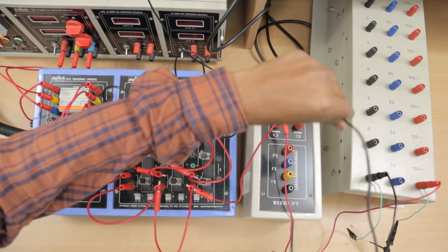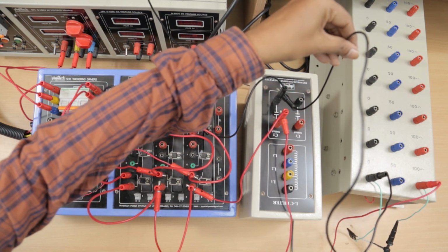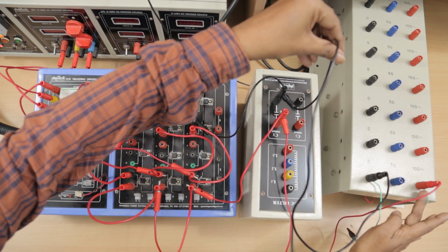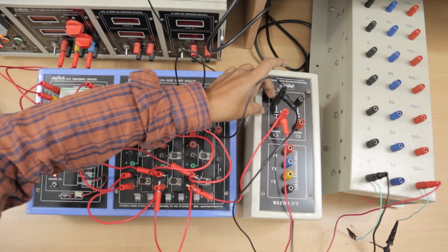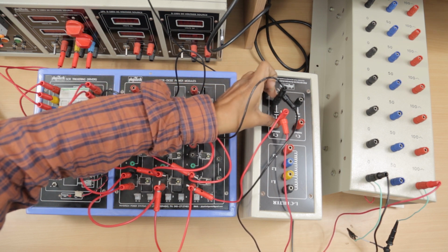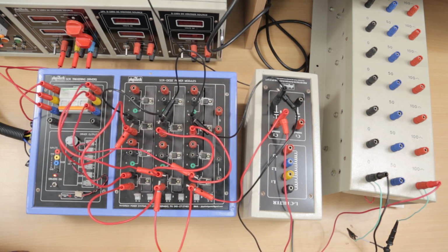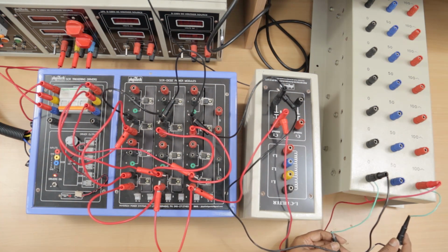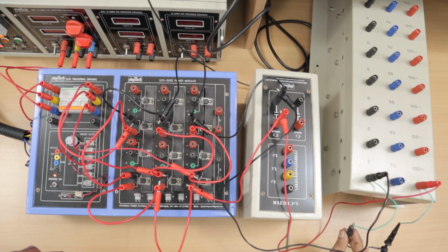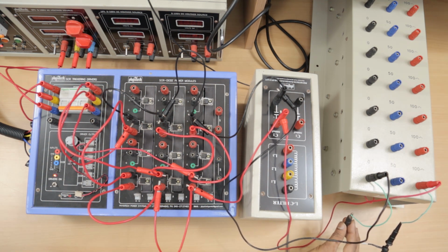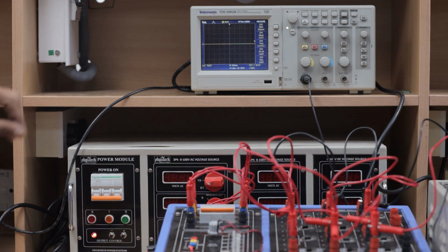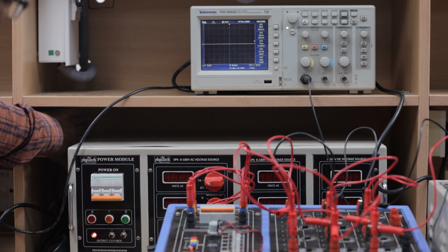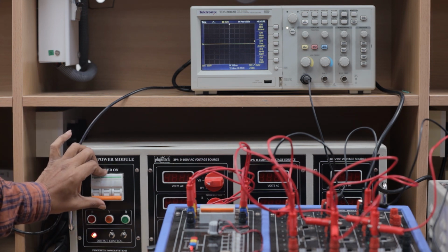Across the capacitor we connect a resistive load. The resistance value is 100 ohms between the black and red terminals, and the capacitor value between black and red is 5000 microfarad. Now connect the probe positive terminal to one resistor terminal and the probe negative terminal to the other. Now switch on the 3-phase main supply, switch on the meter switch, switch on the power module MCB,